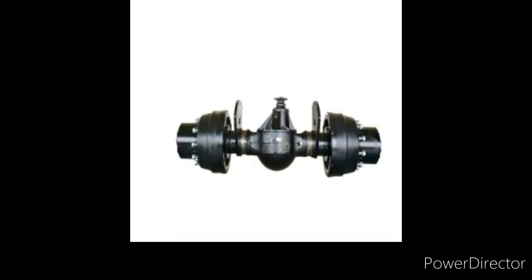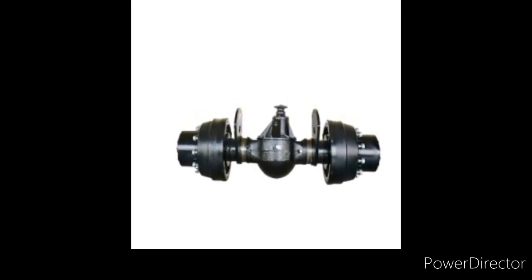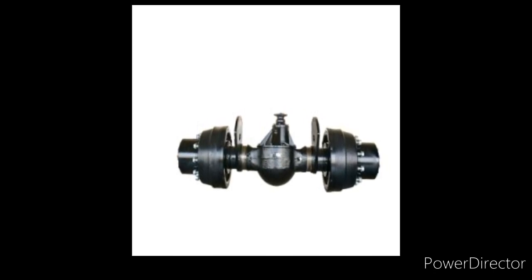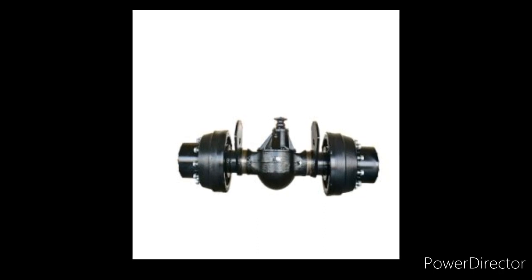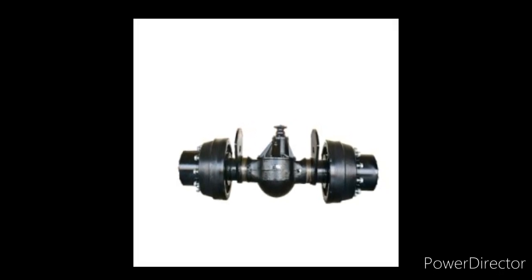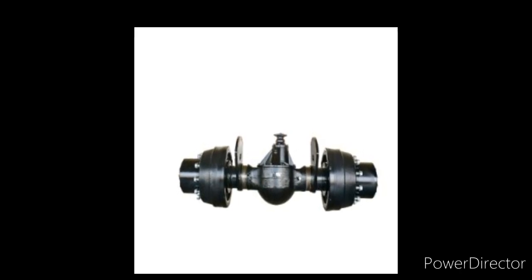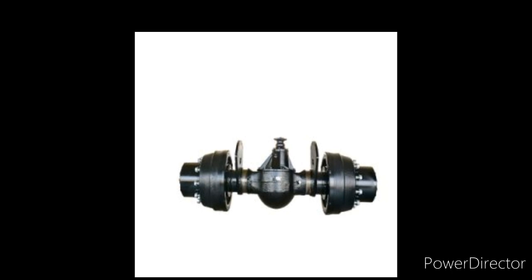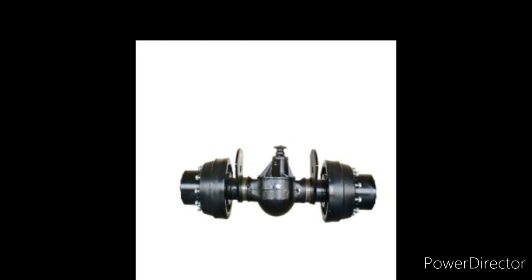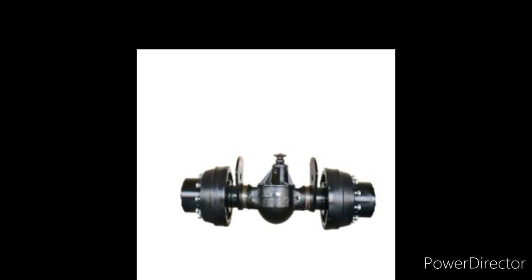Forklift drive axle. The drive axle is the mechanism that accepts IC transmission or electric drive motor RPMs and gears it to rotate the wheels. The drive axle acts as part of the frame and the upright. It also serves as the main cross member of the frame by attaching to the open end and securing the frame sides. Some uprights are mounted on the drive axle, which, because of its massive, hardened metal casing, can handle the full weight of loads.